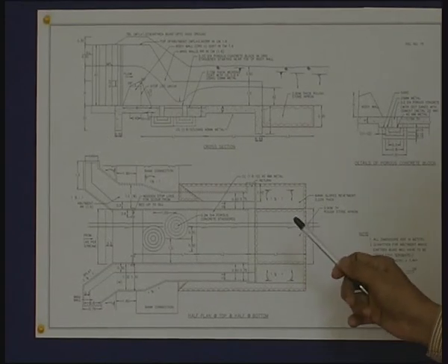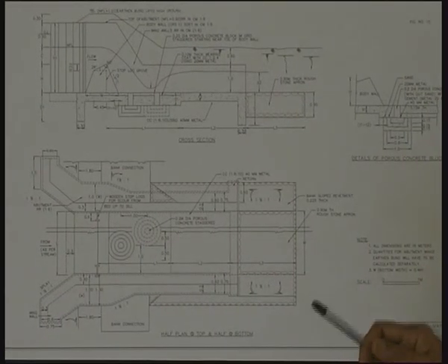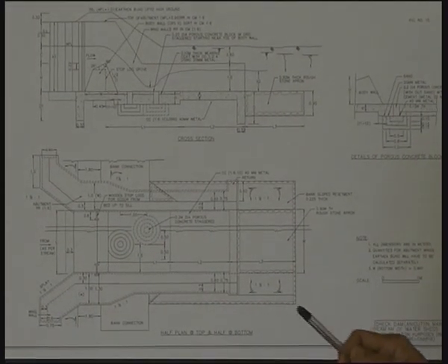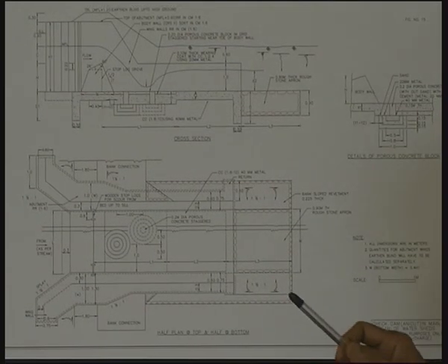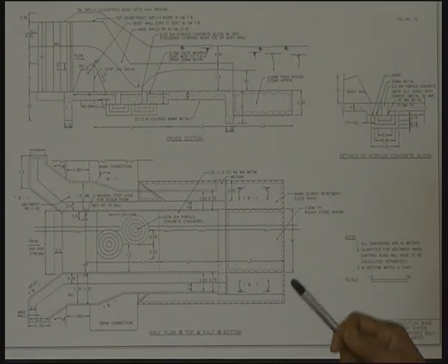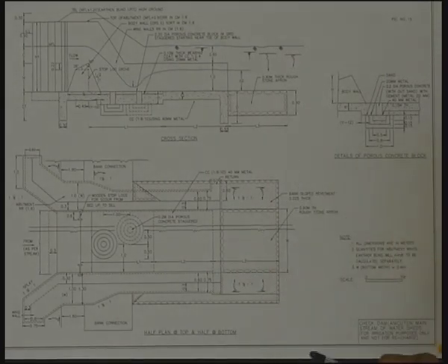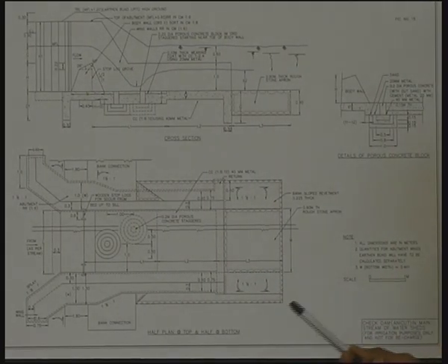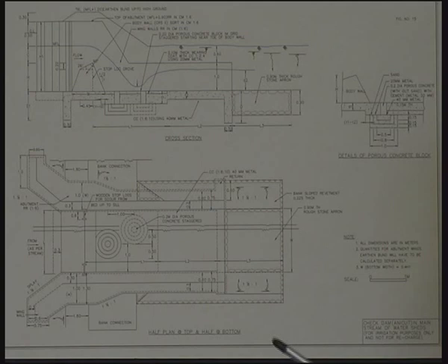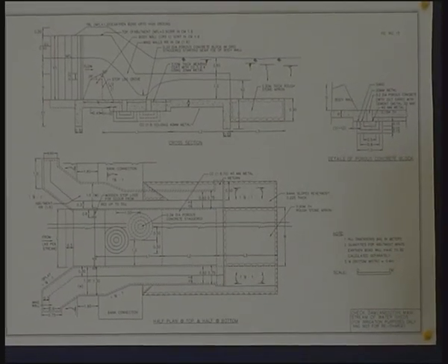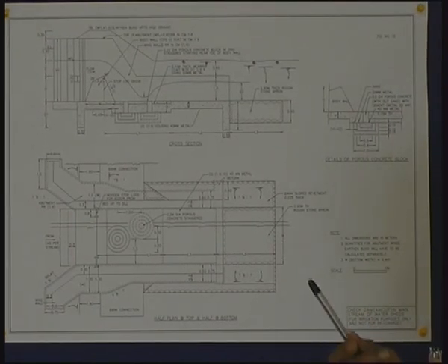So, for any check dam, any cement based check dam which is intended for the purpose of diverting the flows for irrigation purposes, the ready reckoner tables give the quantities of various items of work and also give the various dimensions of the structure. The estimate can be prepared using these tables, and with a minimum amount of training for an hour or two, the villagers themselves or the watershed committee members themselves can prepare estimates and execute work.